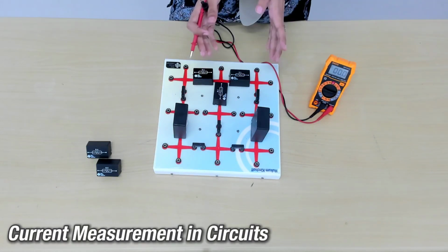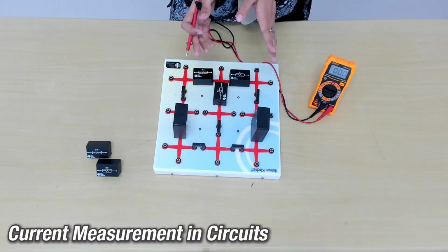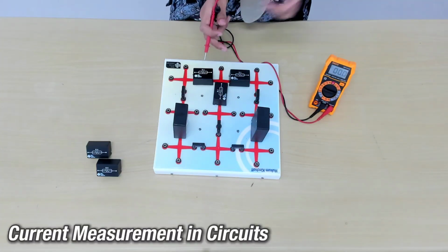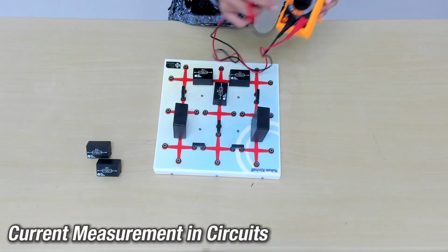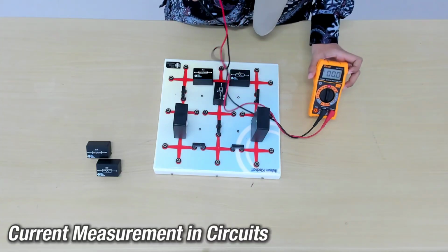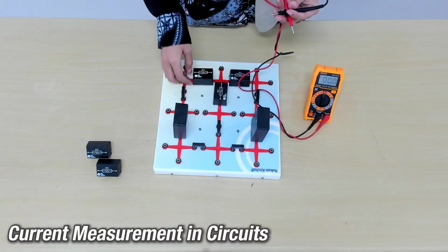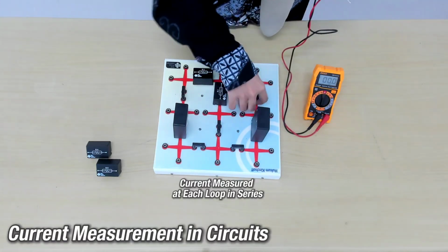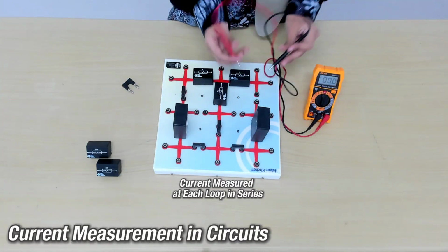Next, to measure current, since there are 2 loops, we need to measure the current in loop 1 and the current in loop 2. Turn the multimeter dial to the current reading. Then unplug one connector from loop 1 and insert the probe.